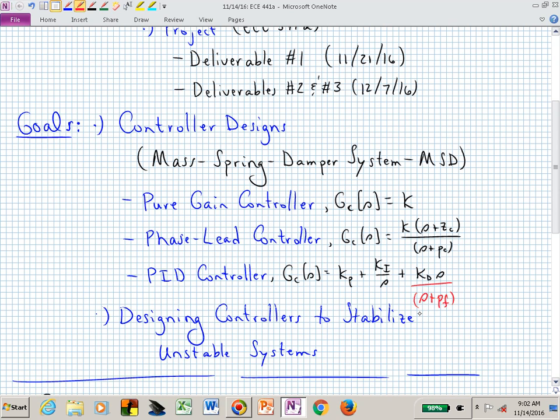a fast pole underneath that derivative term so that we don't have the gain going off to infinity as the frequency increases. We don't want to keep increasing the gain at high frequencies where we might have a lot of noise. And in that sense, we need to at least stop that progression of the K sub D S. If you looked at the Bode plot for that S, what would that look like?